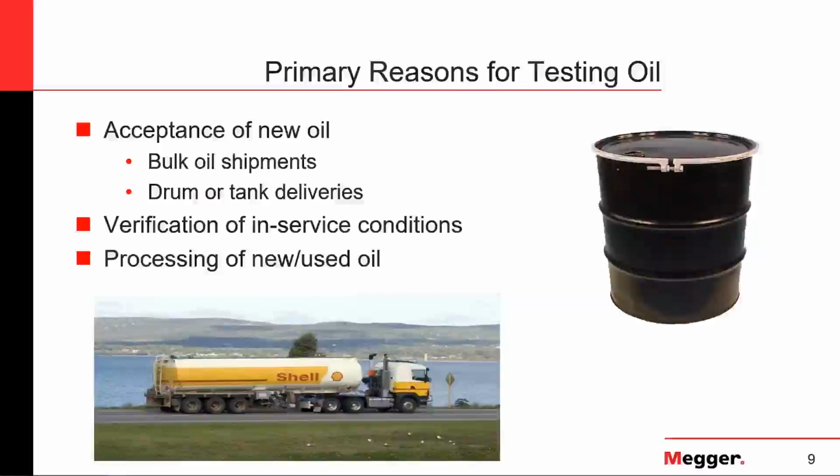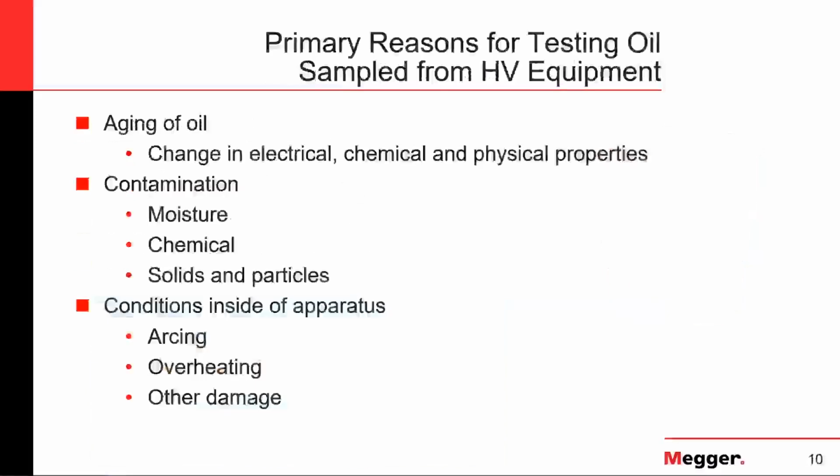So to summarize, there are three important moments to test the oil during the useful life of electrical equipment: acceptance, during service for verification of in-service conditions, and after we do any processing or reconditioning of the oil.